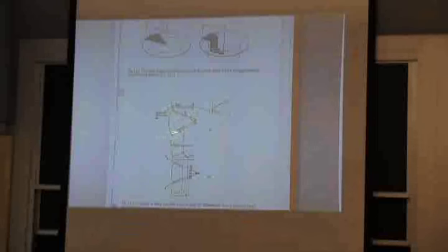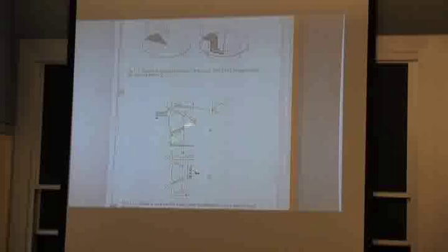If I want to think about this a little bit further, here's my little pie-shaped wedge in my disc, before I draw it, and it has this shape. And Backofen used to like to, he's the only one I know that does this, he used to say, well, that's sort of like drawing a sheet between some conical dies, and I'll pull something and make a straight side. It's like wire drawing, if you will, starting with a conical shaped specimen.